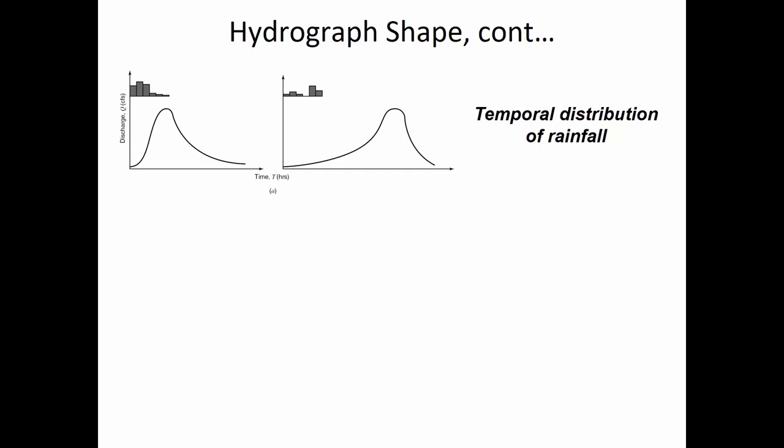Sometimes you'll look at flow data in a watershed and the hydrograph looks different from some storm that you were looking at months or years earlier, and you wonder, why does the hydrograph look so different? In the 24-hour period, they were both 3-inch storms, but it's often because you may have daily precipitation data, but the 3-inch storm from last year could have been completely different from the 3-inch storm this year. Last year's storm could have been one where of that 3 inches, most of it was in the morning, whereas this year's storm, maybe the 3 inches was mostly in the afternoon. And so the stream response could be dramatically different just because of the temporal distribution. So temporal distribution means the variety in amount over time.